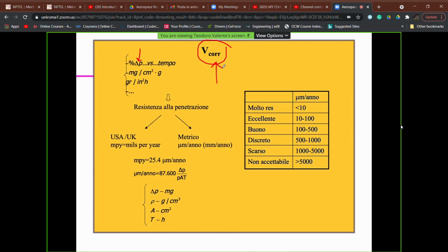So in terms of severity of the corrosion, which is the aim of defining the corrosion rate, the case in which this material is going to lose 1 gram in 1 day, but with an exposed surface of 1 square meter, just to give you an example, is obviously substantially different from the case in which we have a loss of 1 gram in 1 day, but the surface to which this material loss is referred is not 1 square meter, but, for example, 10 square meters.